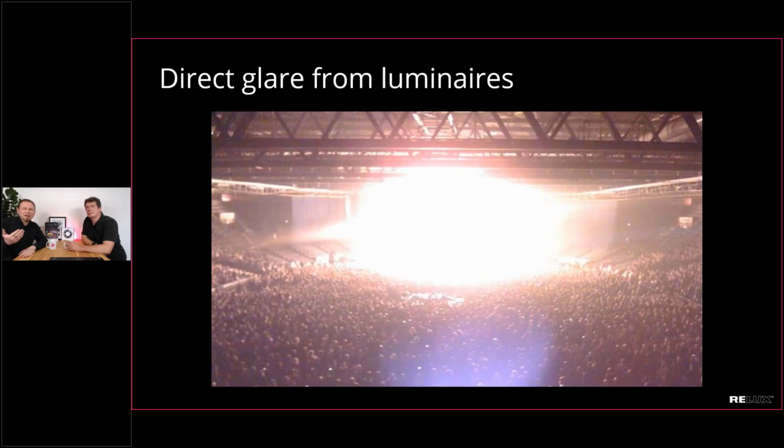This first slide is about glare in general. There are a lot of different glare options, and here we can see a sample of direct glare from luminaires into your impression of the scene. Direct glare means direct harm of light into your eyes from a luminaire, not from sun or daylight. For daylight there are different methods, DGP for example, which is also included in RELUX. But UGR is just about artificial light, indoor. Mostly, it's also possible outdoor, but we will see some restrictions on this.